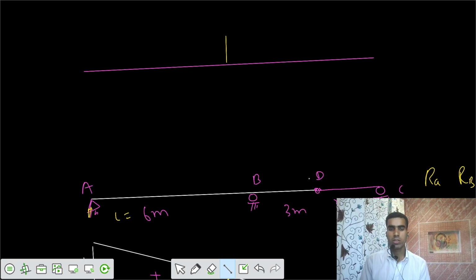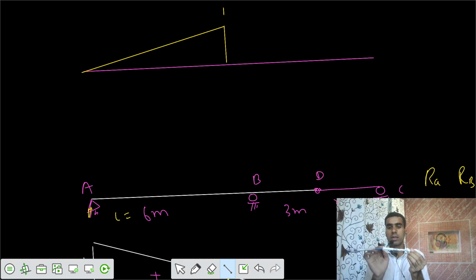So we remove the support at B, then you apply unit displacement in the direction of reaction. So this is your unit of 1. Then after that, you keep the other supports intact. Once you keep this support A intact, that means the profile would be in this fashion. After that, because there is a continuity of BD and there is an internal hinge also. So we have B, A, B, internal hinge D, and support C. So you apply unit displacement upwards of unit 1 at point B.